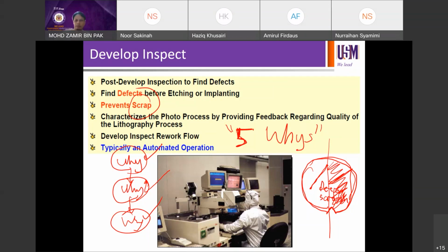Okay, so when you have a problem in engineering, it's very useful for you to understand these 5 whys. Why is it so? Then you get a result. Oh, this is probably due to... why is it so? Then as you go through each why, you can solve the problem that the CD is out of spec. Then you find the robot arm placement is not correct. Then you find exactly it's due to the theta. Then you find exactly due to the belting. And then you find the belting is worn. And then there's no PM.